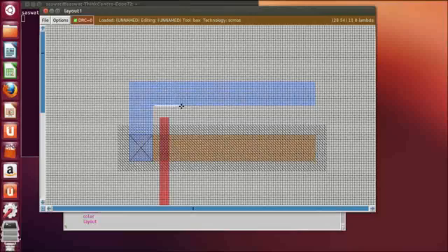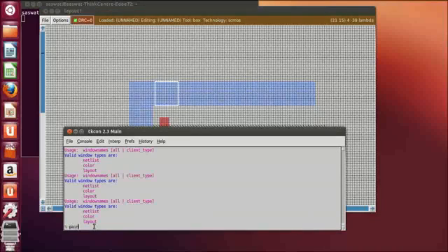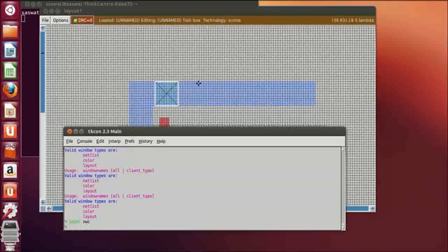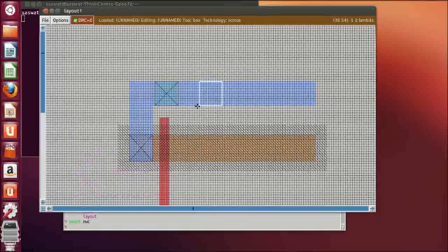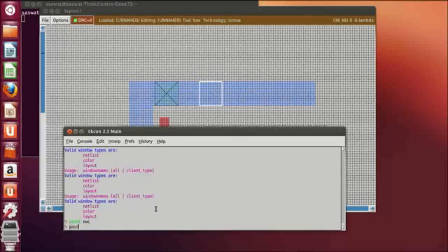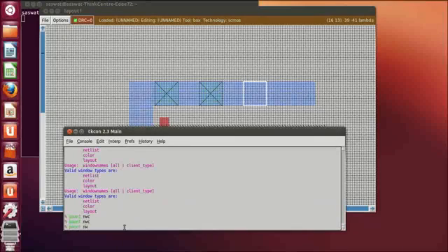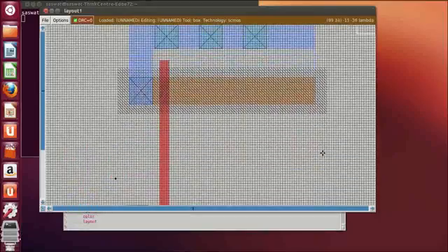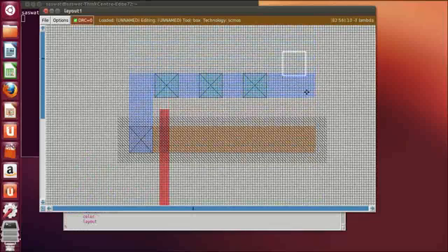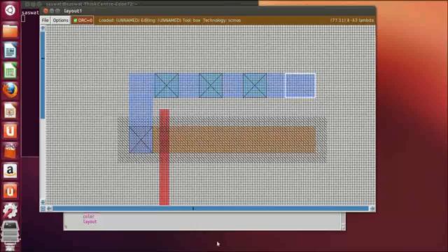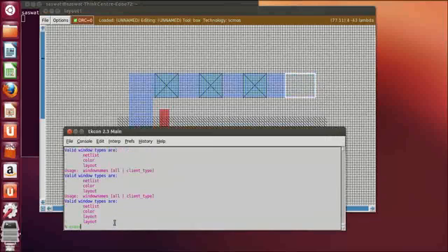Select the area and type paint NWC. We'll place some more. Okay, you can see the selected area is shown every time we left click the mouse. Type paint NWC. Okay, now if we want, we can remove the excess region. Select the area and then type erase.